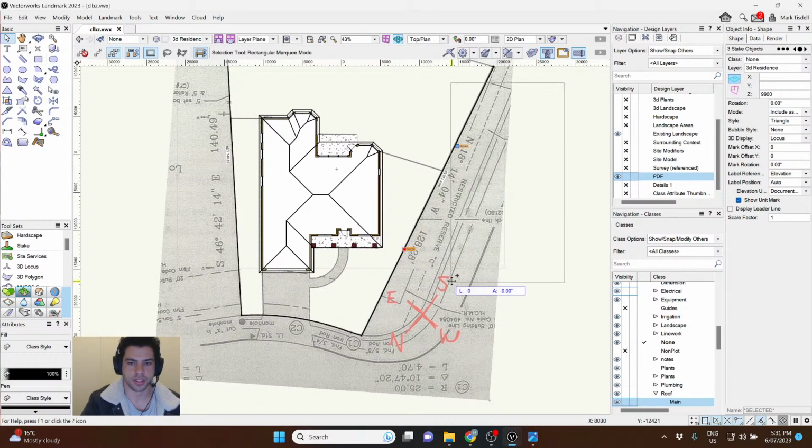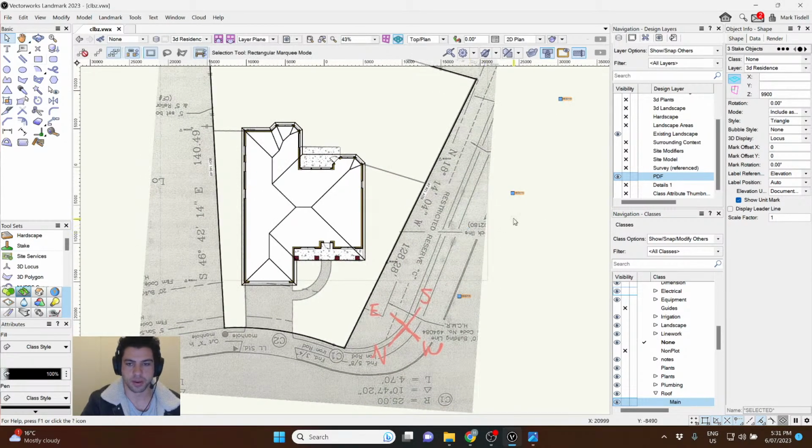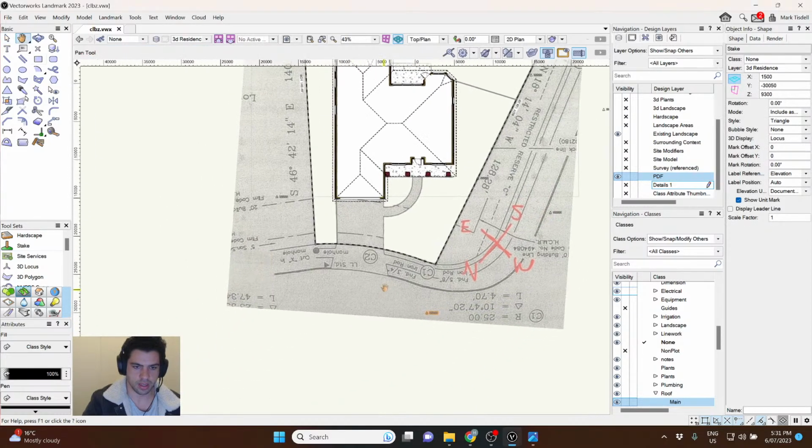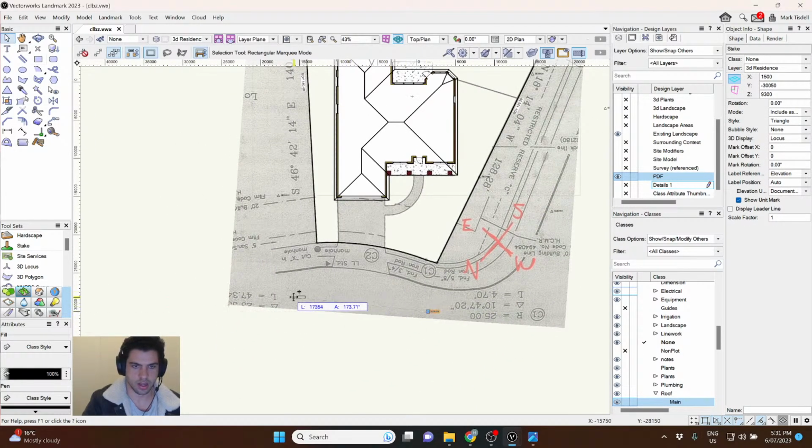My boss at work is like the master of winging site models, so I find that quite impressive. I think over the whole distance it probably goes down, what, maybe a foot, 2 feet. So I might just minus 600 millimeters, which is equivalent to 2 feet. And I'm going to bring this out here and out here.